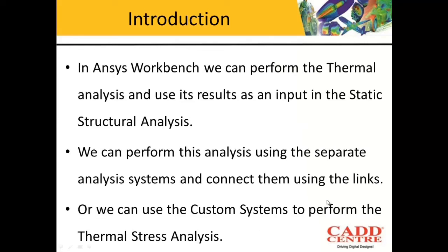In Ansys Workbench, you can perform the thermal analysis and use its results as an input to the static structural analysis. The stress induced in the system can only be found using a static structural analysis, because in thermal analysis you will only get the thermal results, not the structural results, and stress is a structural quantity. So we will have to add another static structural analysis system, and the results from the thermal analysis will be used as an input in it.